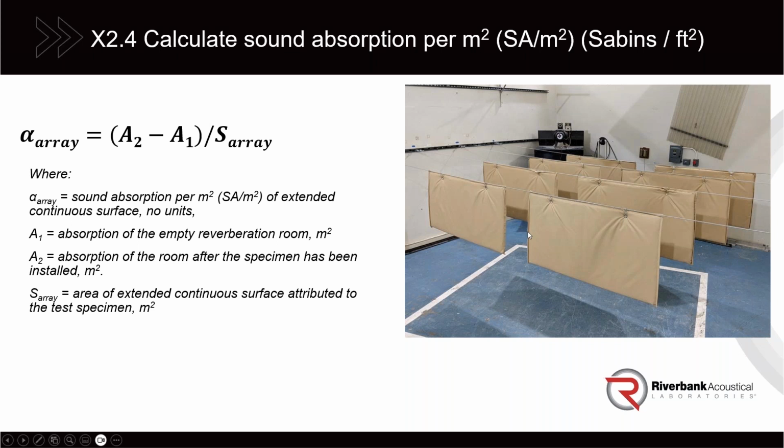Meaning you won't see different results if this set of objects were spaced 12 inches higher or 24 inches higher. They're in the diffuse field of the chamber. But if they were lowered close to the test surface, that reflection off the test surface would start to influence their absorption.